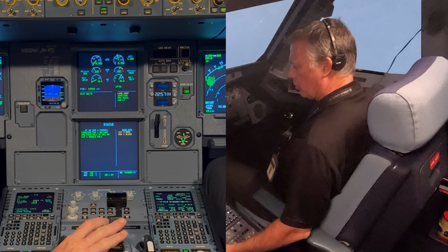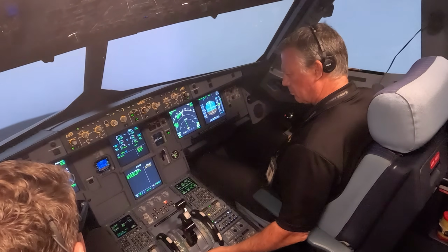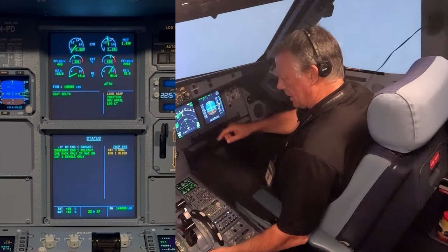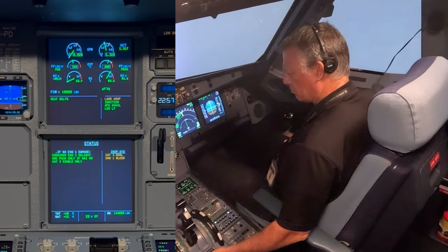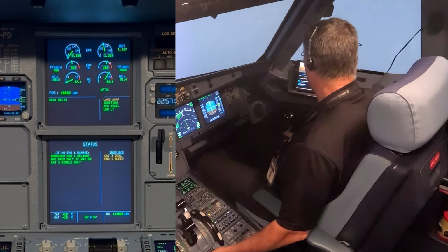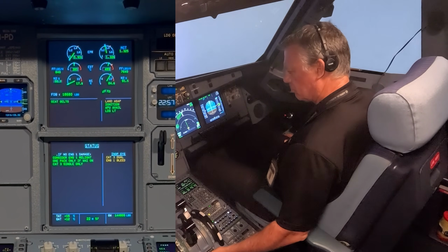Remember to keep your hand on the engine master switch in case of a start fault, which would have to be manually aborted since we're airborne. We'll skip to the point where the engine relight is complete. So it looks like we got a light off. Notice the items on the status page progressively disappearing as the engine comes online.